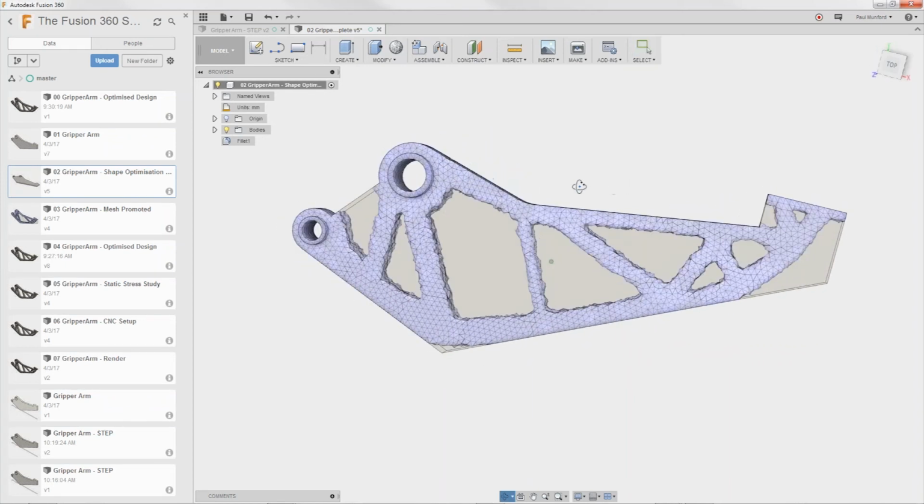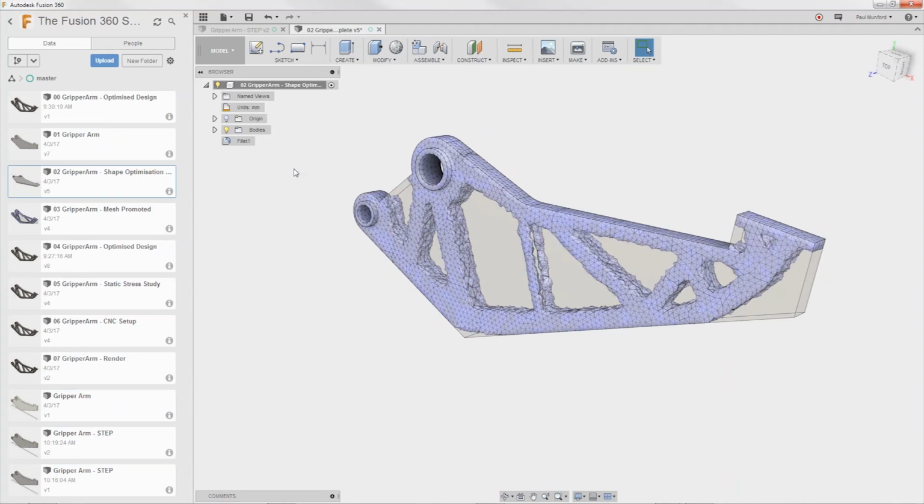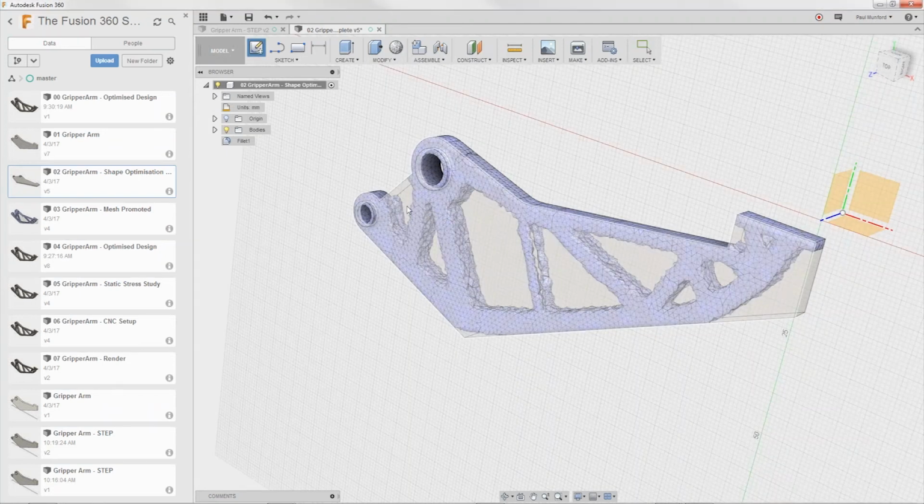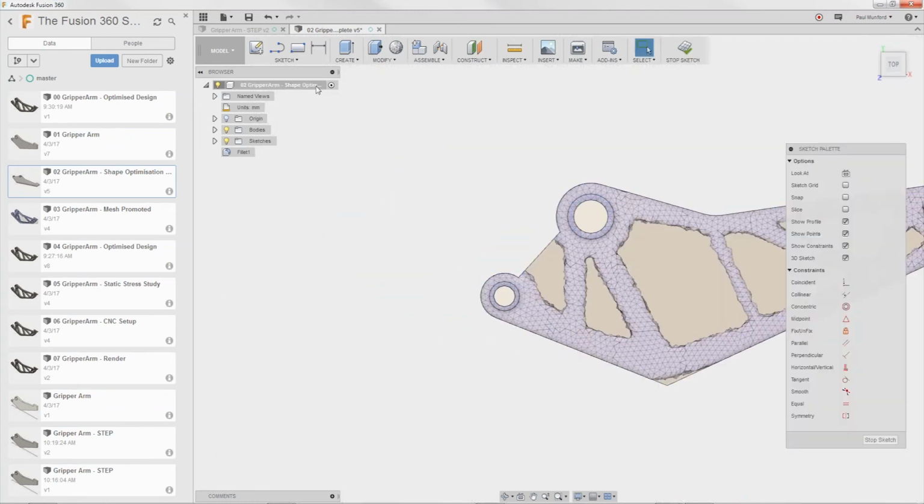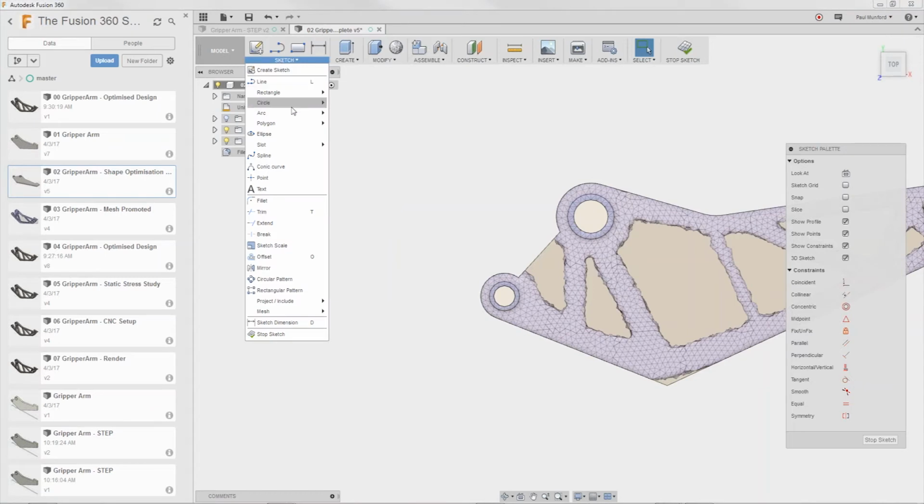So we can take it right back to absolutely the fundamental areas that must have material there, and we could add in a bit more material if we want to achieve a higher safety factor. Notice about halfway up, here's my target. So at that point we've got our 40% material reduction, and we can see down the bottom, mass ratio 40%